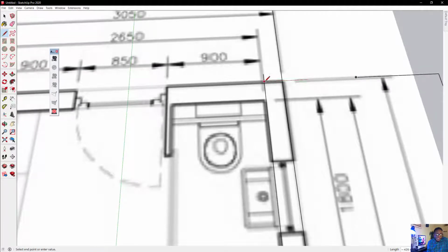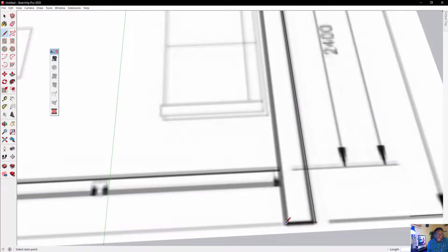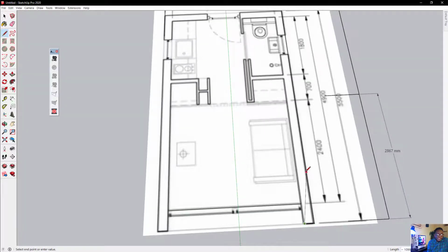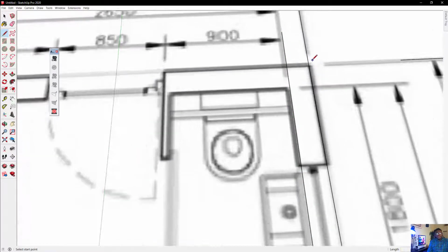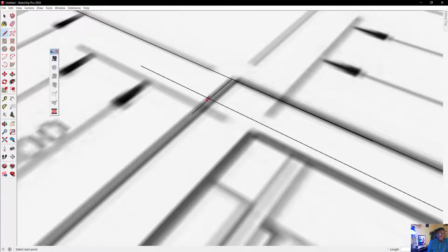Now here's another important tip. If a line is lean, it is going to actually destroy your entire drawing, right? And when I say destroy, I mean when you get to a further point in the model, you're going to realize that your roof and everything is not lining up. And chances are that will happen because from the foundation, some of these lines were actually not accurate. So you want to ensure to use accurate line work. Use lines that are parallel and so forth.